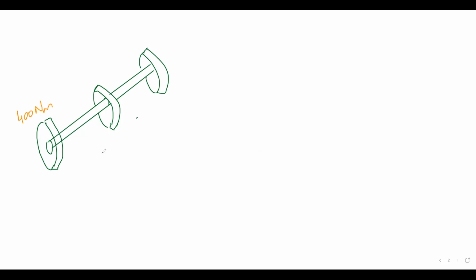Please remember that in most of these problems, we are considering one continuous shaft. The diameter of those shafts can change, okay? But just imagine I have from A to C, with gears here, here, and here, and somebody is asking me for the angle of twist end to end. Of course, this is one piece of shaft. The change in diameter is happening, no problem, but it is one piece.